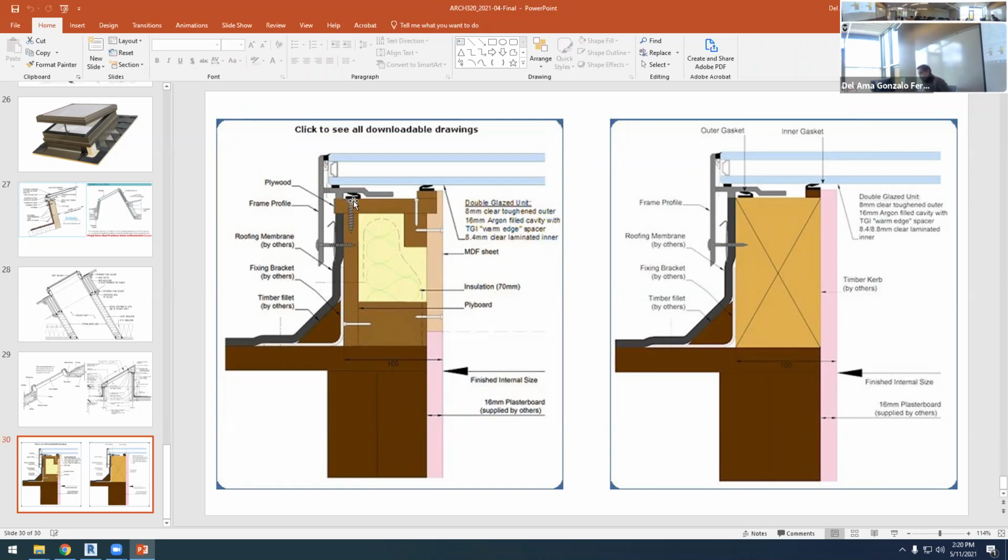You remember that we can use detail components, and then we can change the color of the hatches or these elements. So it's not easy. It takes time, but this is what makes the difference between something well-defined and something that is not. And as I have told you before, if you don't make a decision on where this bolt is or how you connect the waterproof membrane, the roofing membrane, to the skylight, others will do it for you, and it will be worse.